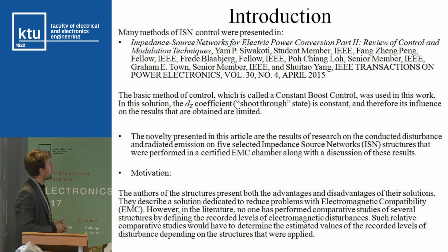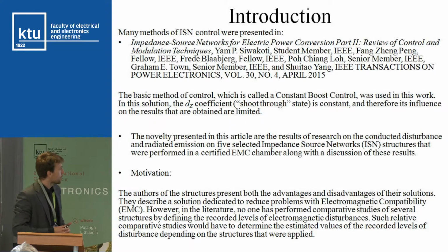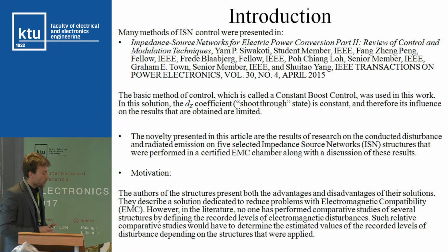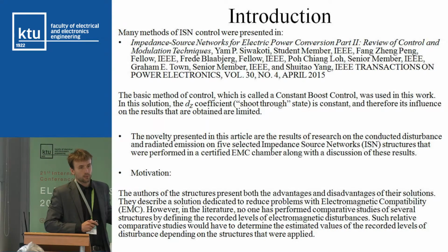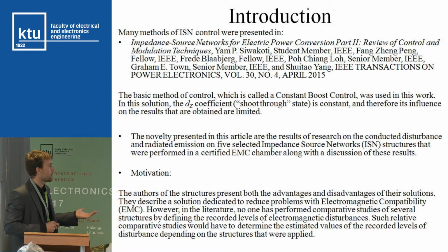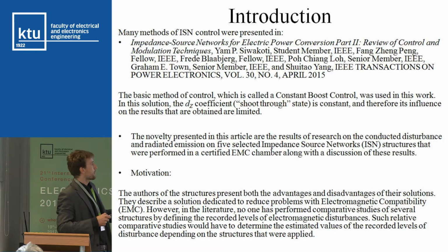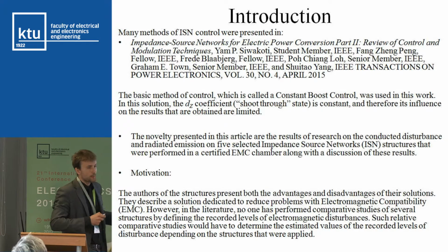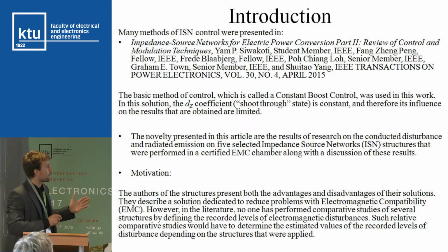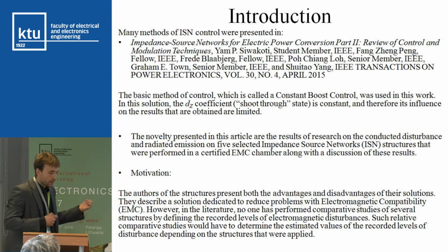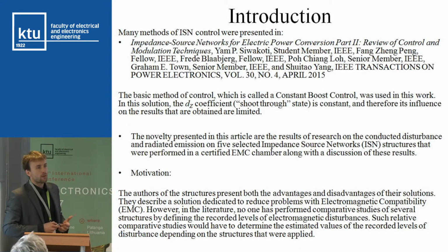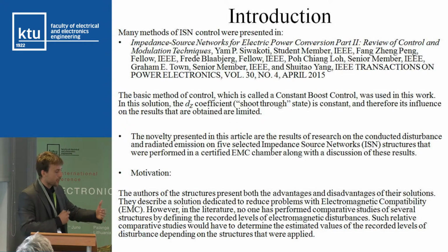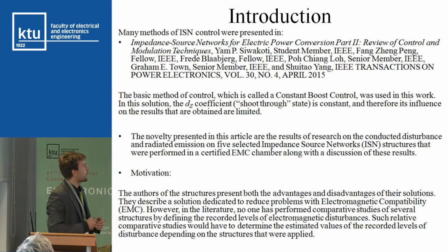In our research, we use only constant boost control. It is the basic method to control the impedance source network. This solution is characterized by the coefficient dz, the shoot-through state, being constant. Why did we choose this one? Because we want to analyze only the influence of the structure and not analyze additional influences.